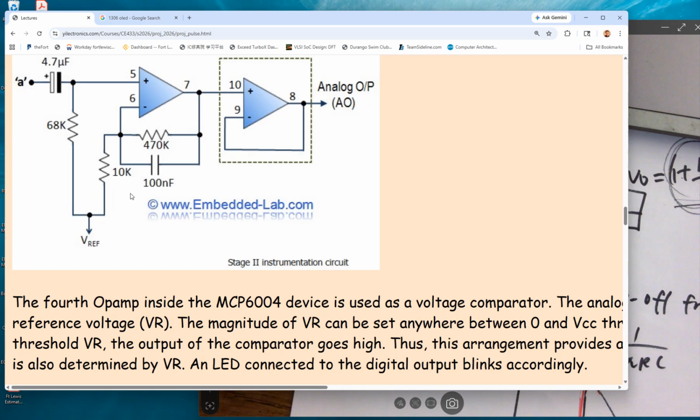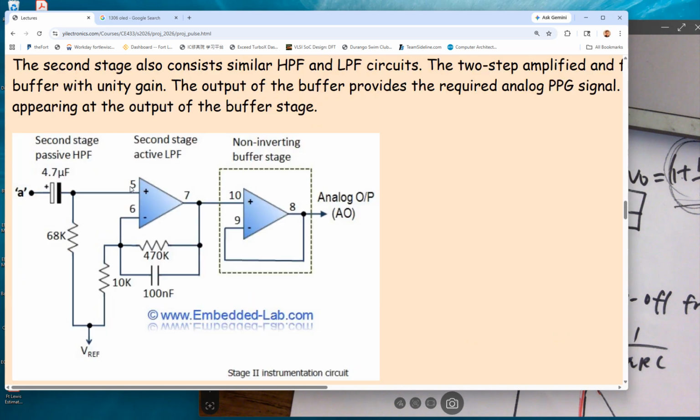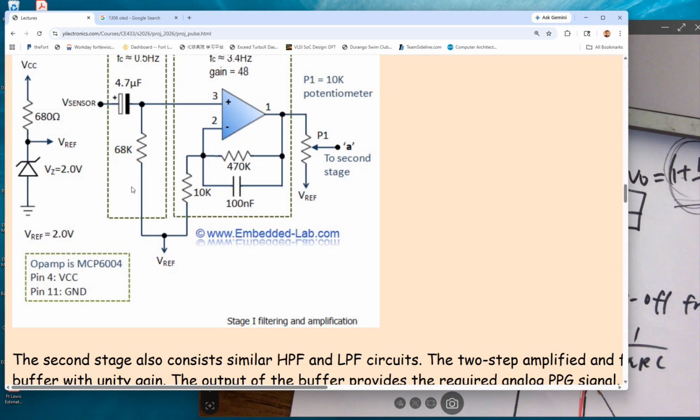You can see a lot of scientific instruments, especially for optical signals with a lot of noises, they do have 4 or 5 op amp stages, exactly the same configuration. And sometimes they do non-inverting configurations, sometimes they do inverting configurations. And if you do inverting configurations, you have to use an even number of these stages, so it's being inverted twice and eventually has no phase shift. Okay, so these are just something to consider in your design.